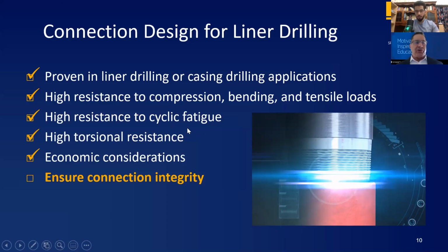In vertical holes, you're probably going to be okay because there's less cyclic fatigue than there would be in directional holes. So these two go hand in hand, but you don't want to run a cheap connection where you're expecting high cyclic fatigue issues. And last but not least, you want to ensure your connection integrity. All this design work does you no good if you don't properly make up your connection at the rig floor. So I hope that makes sense to everybody.